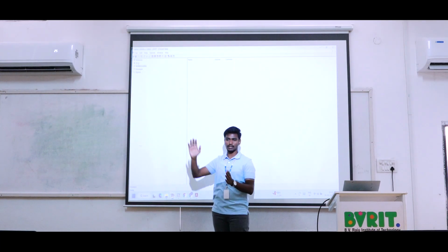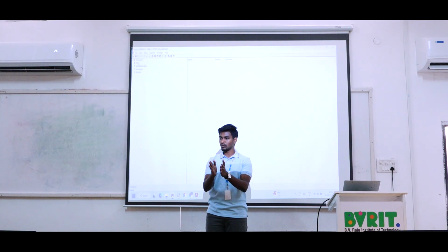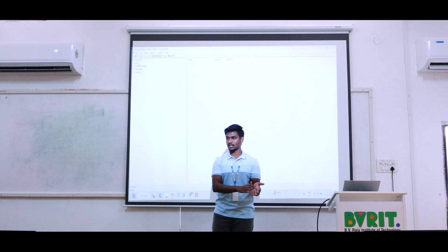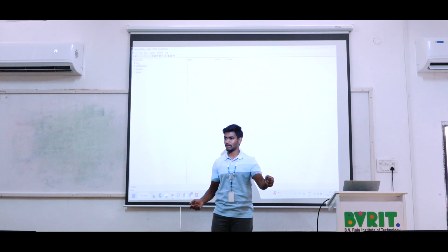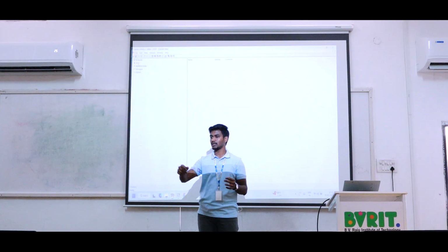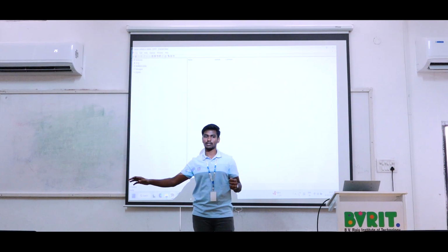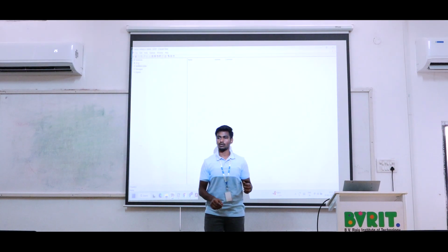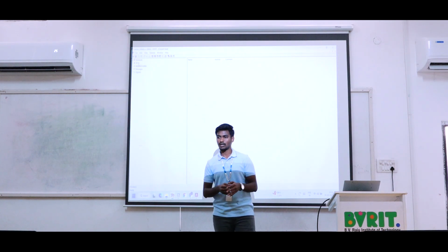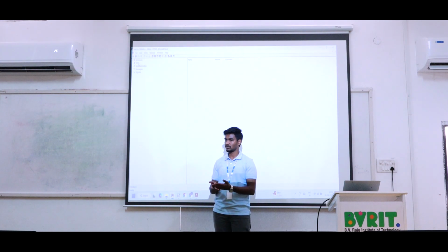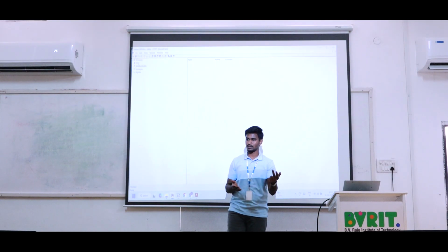For the example, I can take the RKE. We have two nodes here: one is going to transmit, one is going to receive. The RKE is the transmitter, whenever the button is pressed, based on the button values. The receiver is the body control module, which we call the BCM. Unit means nothing but ECU. I already mentioned different kinds of ECUs in our car: engine ECU, transmission ECU, like that.